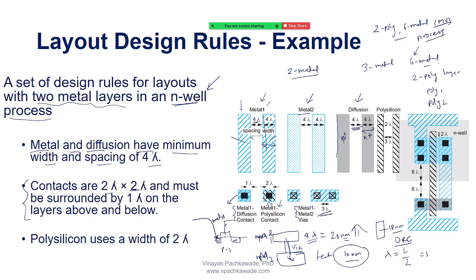So these are the design rules that you will need to obey, and accordingly you will always design your layout. Even if you make a mistake, when you run the simulation or DRC, the tool will tell you that you came across an error. Then accordingly you go back and adjust your widths, adjust your lengths, adjust the spacing between the two layers, and so on.